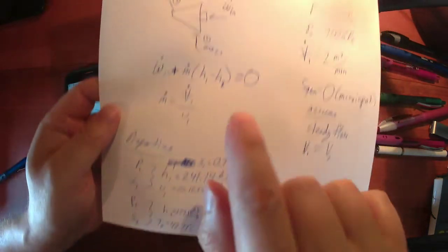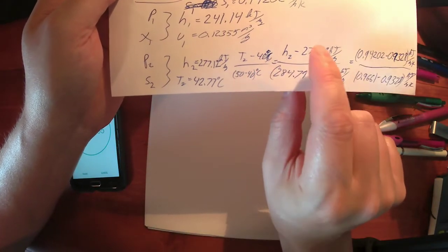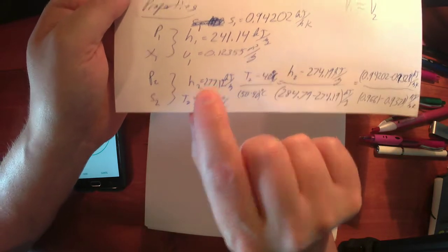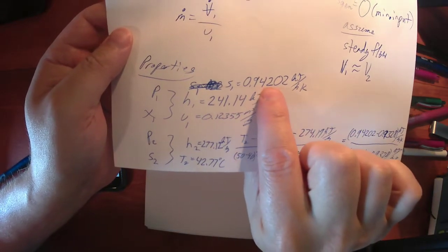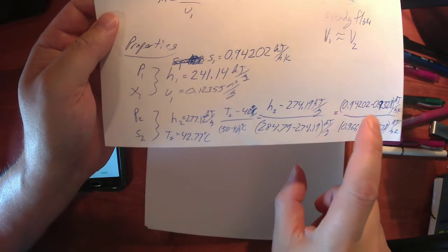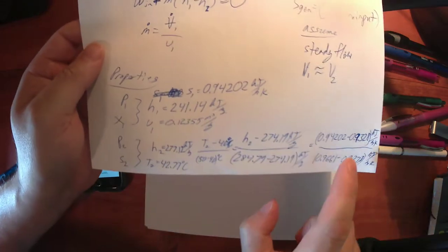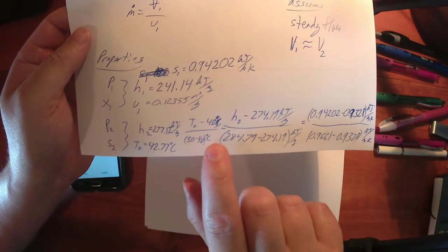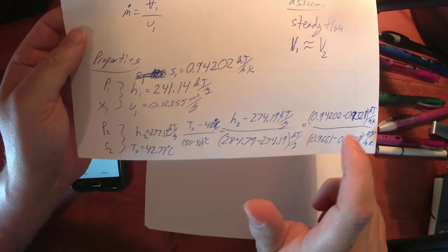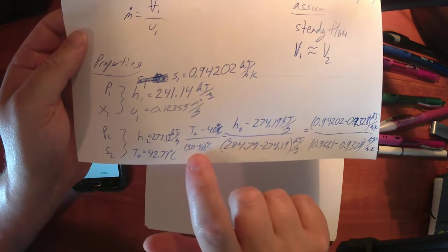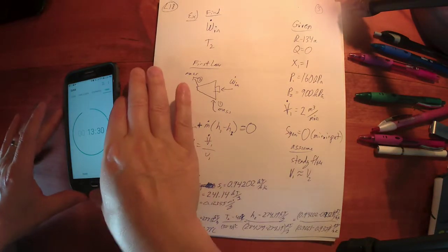we got to find T2. That was one of the things that the problem was asking for. So I had to write out interpolation for the temperature as well as H. Found values there. I've got H2 because S1 was 0.94202. I find that value at 900 kilopascals, right? That value is between the values at 40 and 50. Right? So I've got to interpolate because that 0.94202 falls between 0.9328 and 0.9661, the values at 50 and 40. So I've got to interpolate both H2 and T2 between those two.